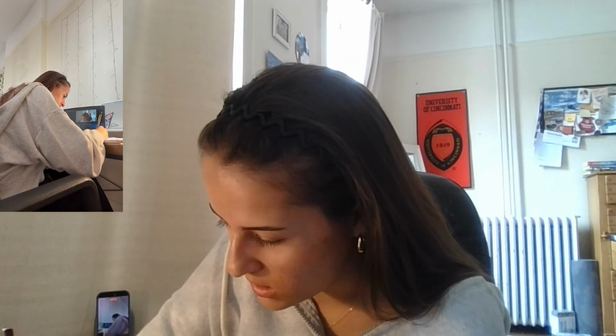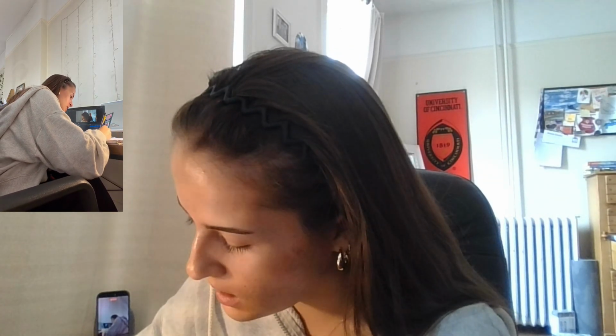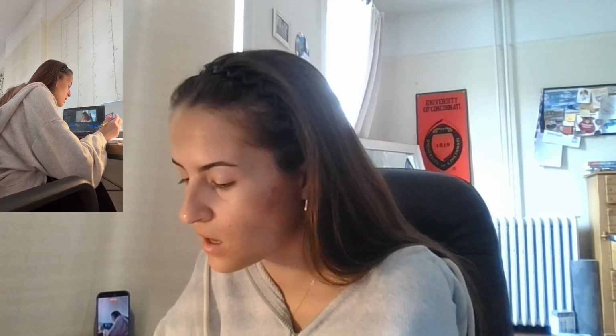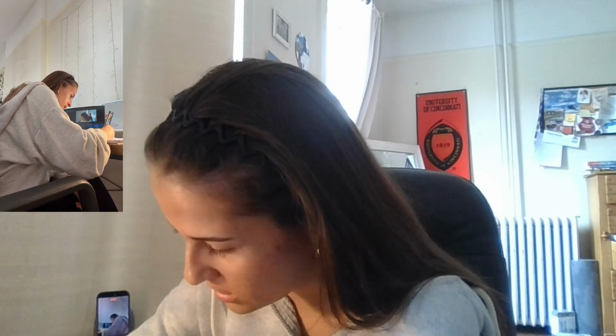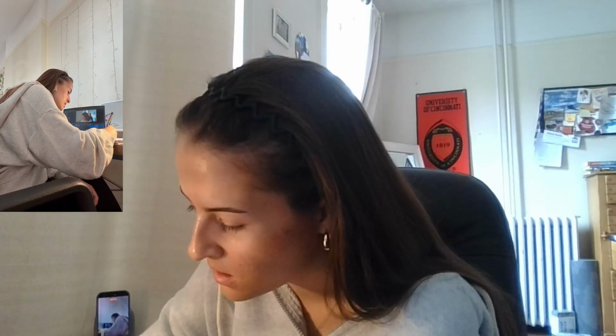So if we do all of this rearranging, we're going to get dTW over dZ is going to equal, so we'll have our packing area, the big A will cancel out, and then we have H over, and then TW minus T air. Our dZ has been divided out to the other side, so we don't need that.